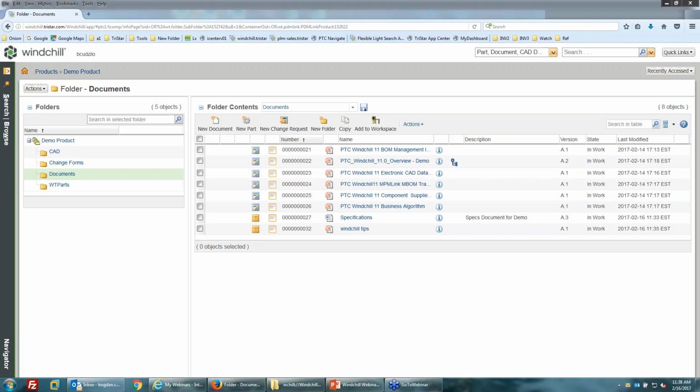So it's great for AutoCAD files. It's great for simpler reference kind of files. But if you want to recreate an assembly structure, part-to-part references in Windchill, I would not recommend doing that manually as documents for those CAD files. I would just use the workgroup manager.